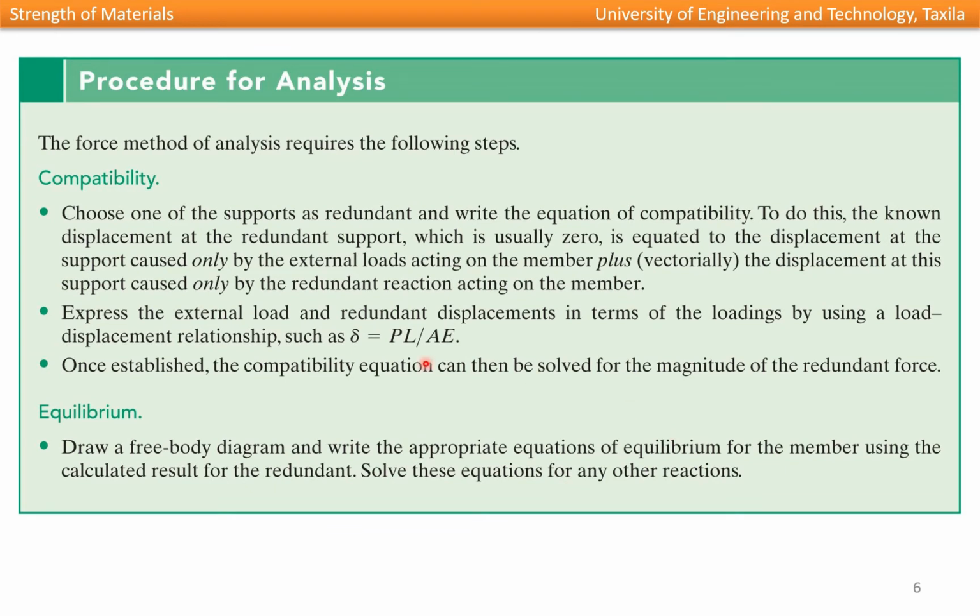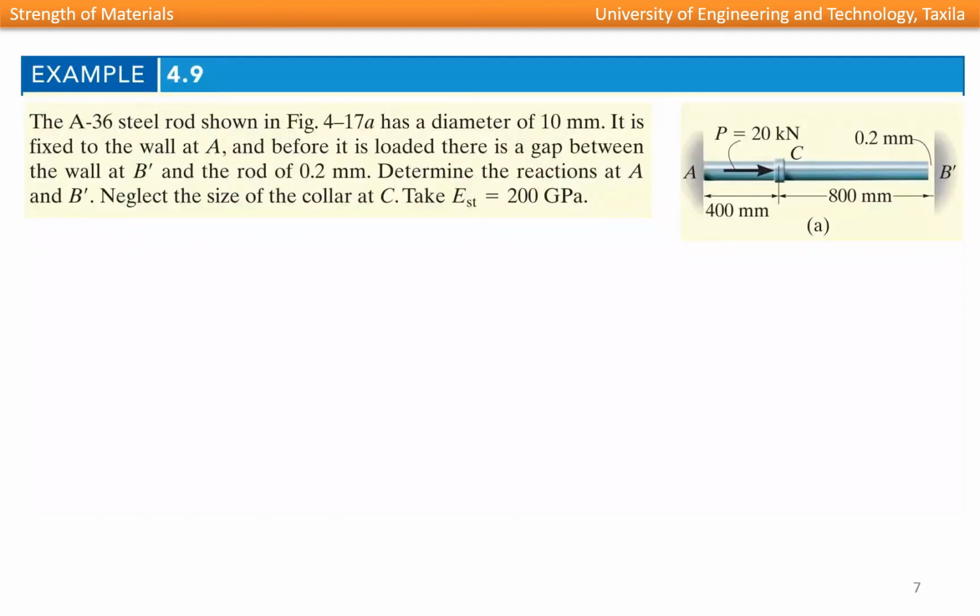So this is the procedure for the analysis of statically indeterminate problems using the law of superposition or force method. Here we first write the compatibility equation. In contrast to the previous method, where we first wrote the equilibrium equations and then the compatibility equations, in this method we first write the compatibility equation and then the equilibrium equation.